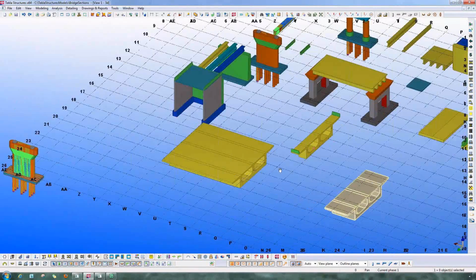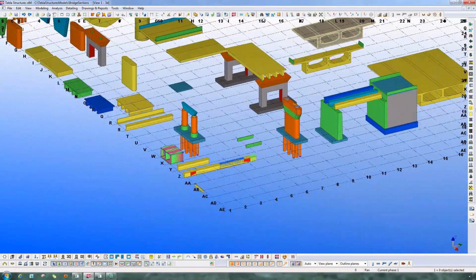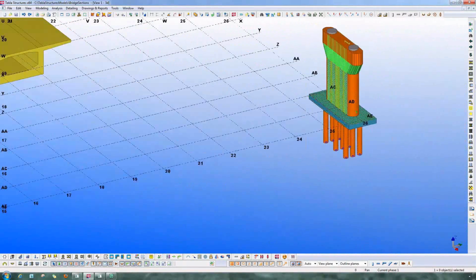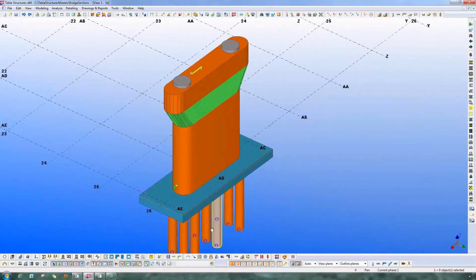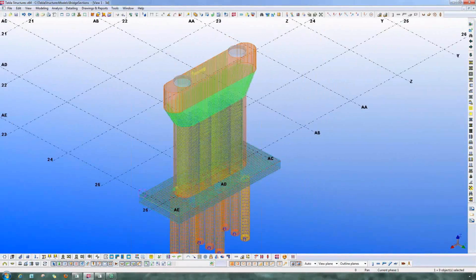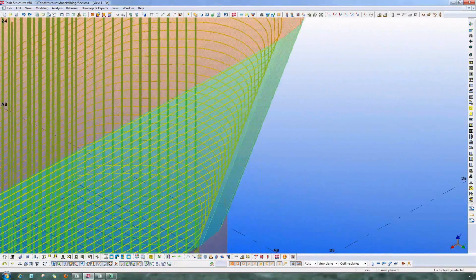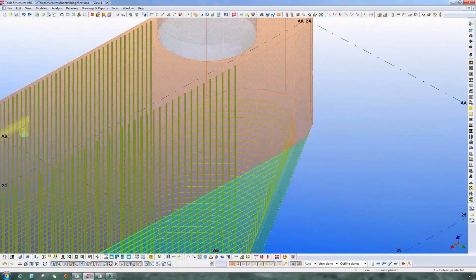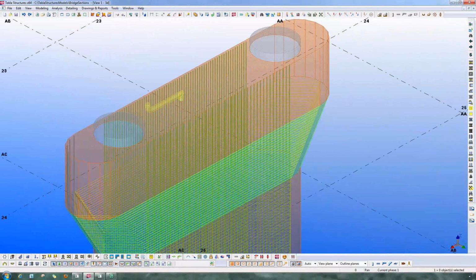And coming to the reinforcement side, first I will start with the one I already have, with the mat foundation with the piles and the pier. I'll be showing the reinforcement part where, in the slope portion, we can see the pier has a tapered portion, and we have the reinforcement modeled, the circular reinforcement, and even the vertical rebar, and even the drainage also modeled here.